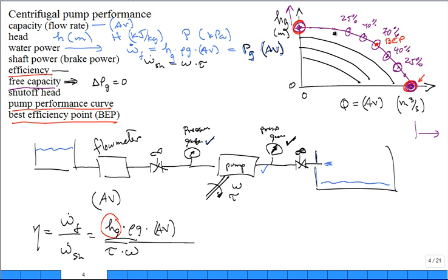And so each one of these will have a best efficiency point, and they'll have a recommended range of operation. The way they do that is they look at the flow rate at the best efficiency point. They multiply by 1.1, so about 10% higher, and then by 0.8, so 20% lower, and they say, if you want to run with that impeller and that casing, try to stay, as a design engineer, in that vicinity. Don't go to the other parts of the curve. It's not worth it, okay? Operate close to the best efficiency point around that curve.